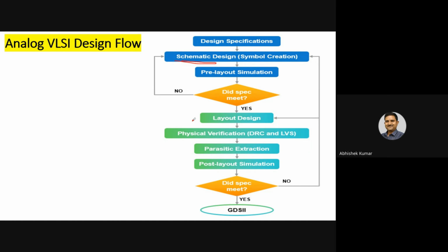Layout is the physical design, so before layout we go for pre-layout simulation. Then again one question: have the specs that we started with been met? If no, change the schematic.